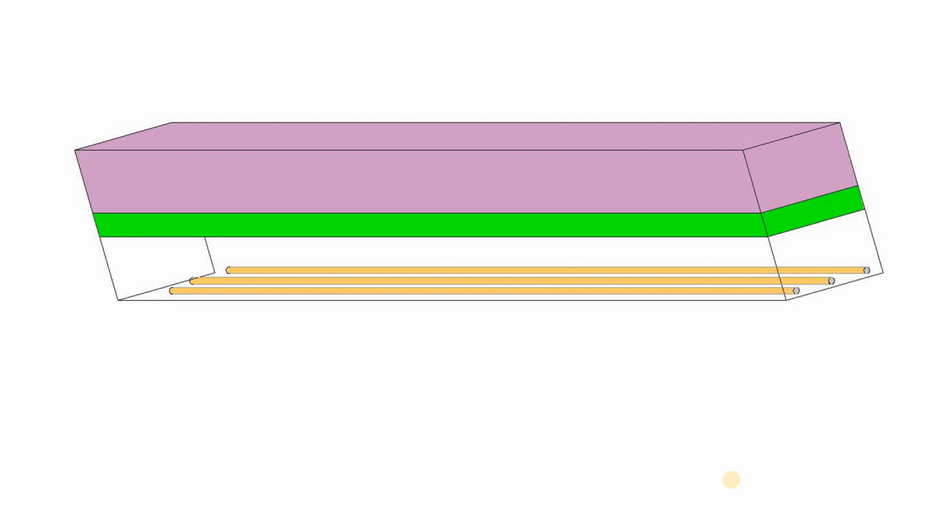This steel reinforcement must be placed at a distance at the extreme end of the beam. So we can take this cross section. The reinforcement must be placed at the extreme end of the beam in the bottom zone so that the tension force is nullified. When we do so, the reinforcements have a threat that they will be exposed and rusting will happen. Instead of placing the reinforcement at the extreme fiber, we have to place it at some distance away from the extreme fiber so that enough concrete is embedded and the reinforcement is not exposed to rusting.